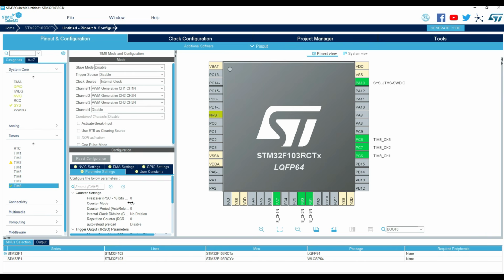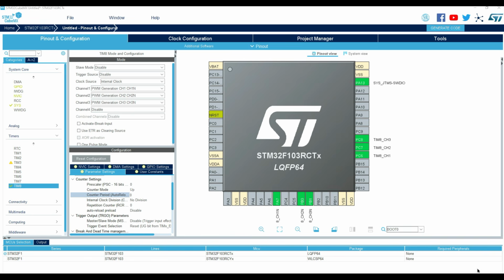I already told you, so we use some values. Prescaler is 0. Later on we'll set the prescaler here. Then the period, ARR, we'll set to 4499. So auto reload will be 4499. This means 72 megahertz divided by 4500 gives us 16 kilohertz. And this means 0 to 4499 is its resolution, very smooth control.